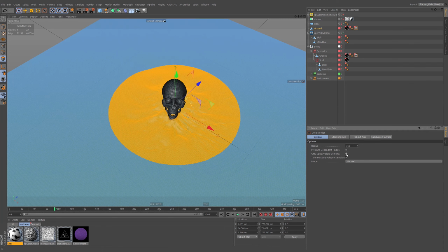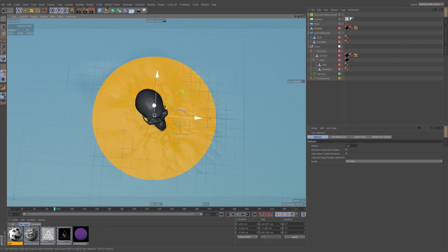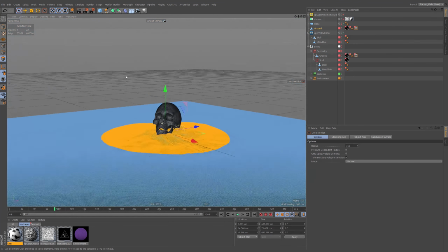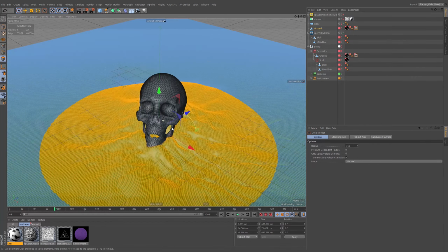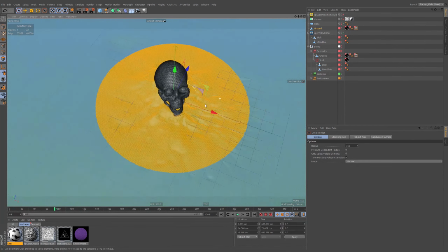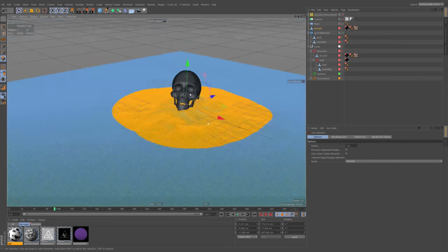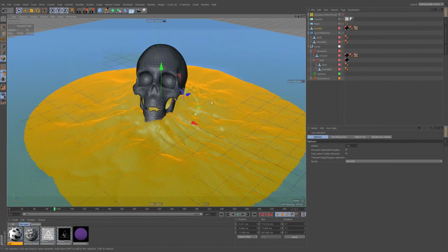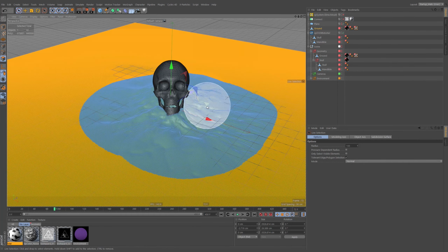I need to turn on only select visible elements. So I'm just going to do that again. This time, I'm just going to select it there. And then I'm going to invert. Now this is just to make the volume operation a bit lighter and quicker. Oh, I might want to grab a bit more of this area around here that has some detail. Your mileage may vary. If you've got a different scene, just make sure that all the objects are continuous like this. Now I'm going to invert, so UI is the shortcut for that. That's just invert selection. And then I'm going to hit backspace.